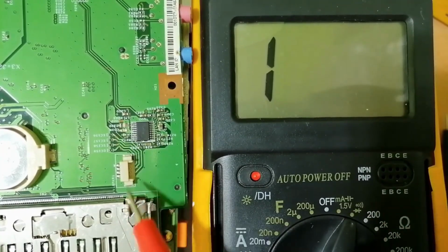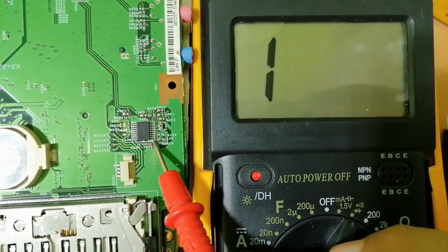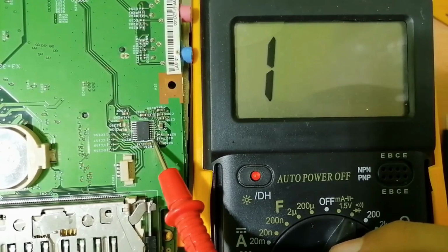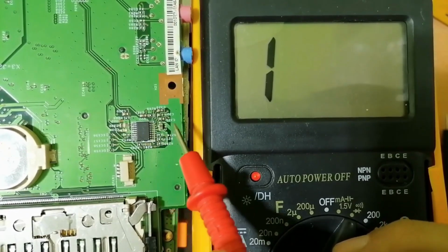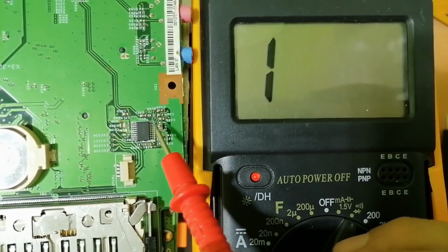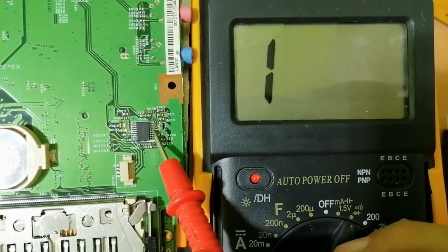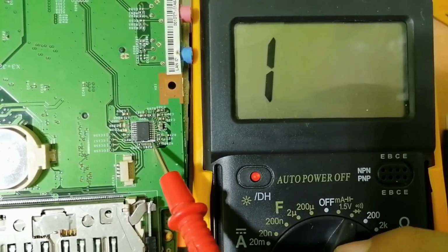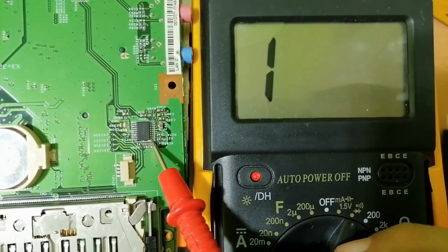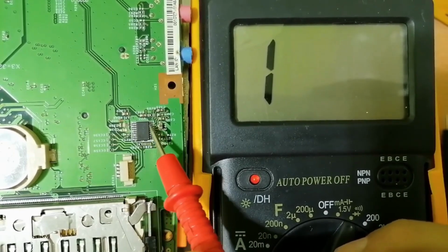So the third method is by checking the inputs and the output. Let's assume, for example, that this is the input of the IC in this pin, and the output, for example, is 3.3 volt. To get 3.3 volt here, the IC first should receive the input signals, including the input voltage, the VCC, for example 5 volt. If 5 volt is missing here, it is impossible to get the output. So when you don't get the output, it doesn't mean the IC is bad or failed. No, you should go back and check all inputs.